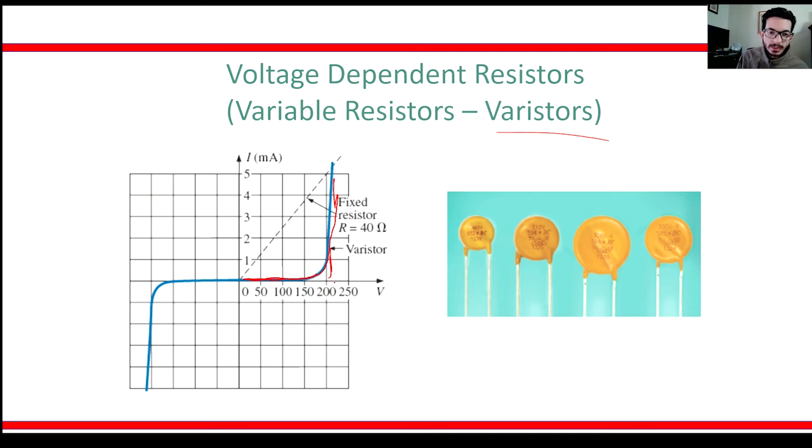But if for some reason there's a short circuit or whatever, and the voltage increases, if you have a surge of voltage and from 200 you go to 210, then you will basically go high on the current, and you don't want this. So you would have a resistor that basically will shut your circuit at 150 or 200, and if it goes above, then it will shut down your circuit. So this is a non-linear resistor application called a variable resistor or varistor.